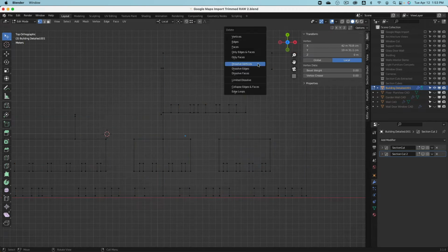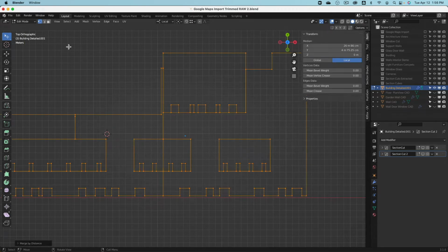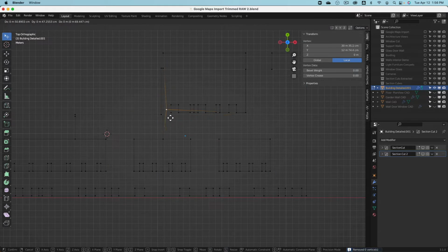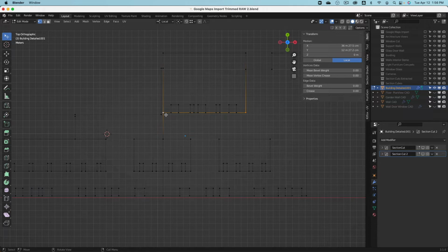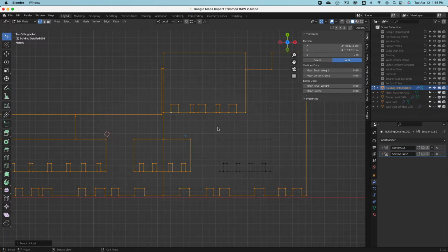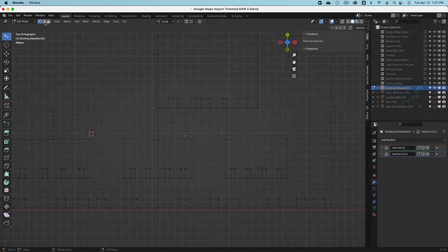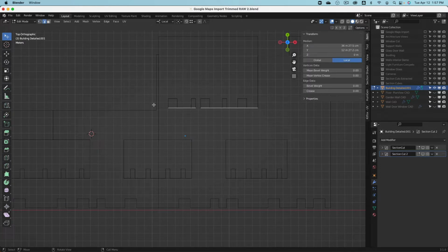Okay, also maybe, oh, there's another one. And then we can go to mesh and do another cleanup, merge by distance. So then this might or might not work. Okay, now here you see, for example, how this line was projected, but these window elements are maybe not selected. So this brings up another interesting point. How do we continue here? So this is actually the edge we would see also with these openings.